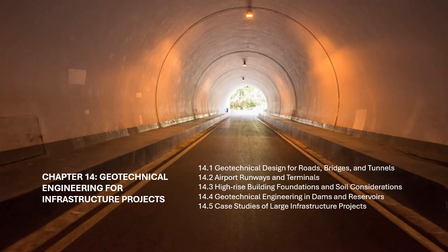Drainage systems. Adequate drainage is vital for the long-term performance of runways. Water accumulation in the subgrade can lead to soil weakening, frost heave, and pavement distress. Engineers design drainage systems that include surface drainage, e.g., slopes, channels, and subsurface drainage, e.g., French drains, perforated pipes, to manage water and prevent soil erosion or moisture-related problems.